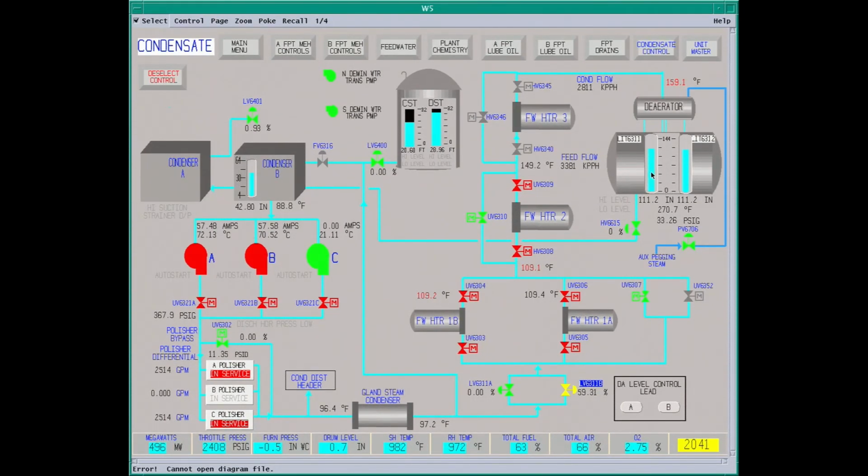But like our whiteboard showed, you lose steam flow and you shoot water in here. It's going to condense all this steam and it could do some damage. So big thing, you don't ever want to fill these with steam, then hit them with water. You want water on and then slowly open the steam to warm them up, clean up the water.